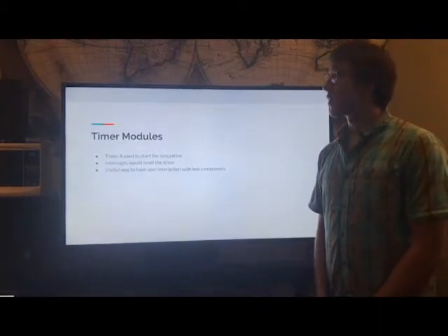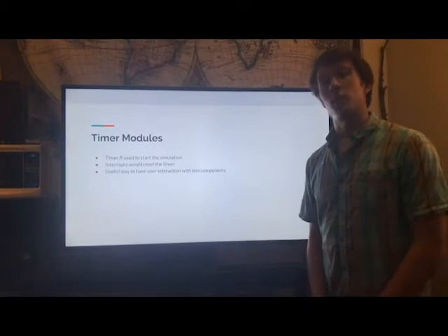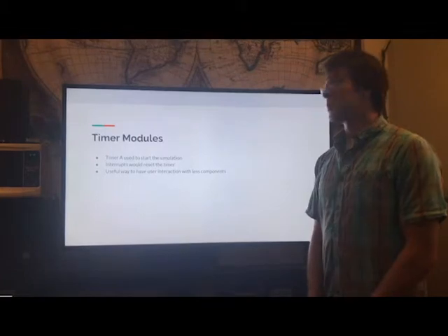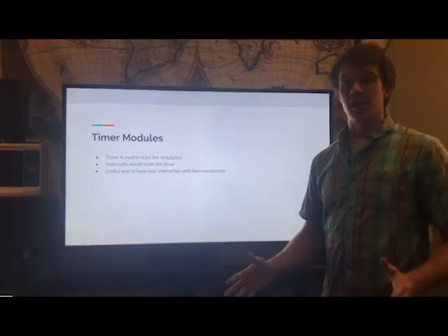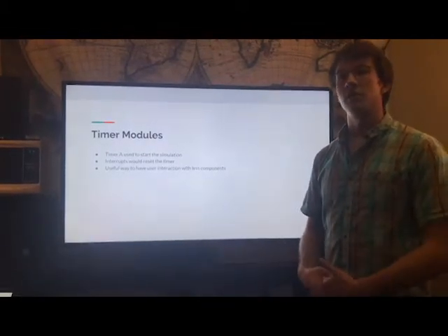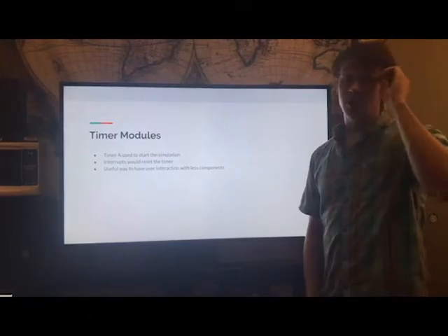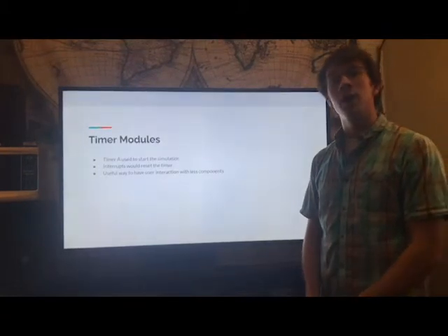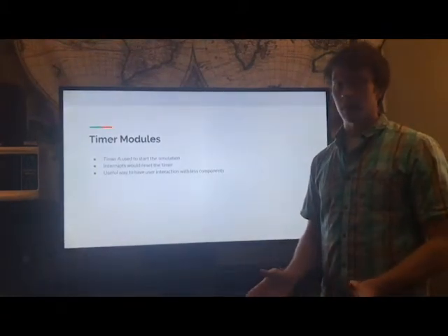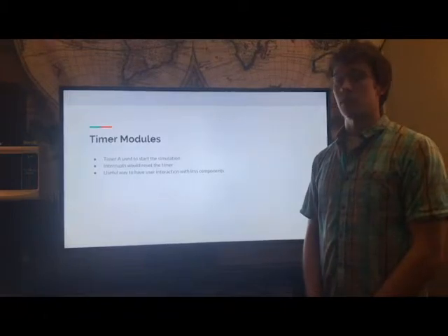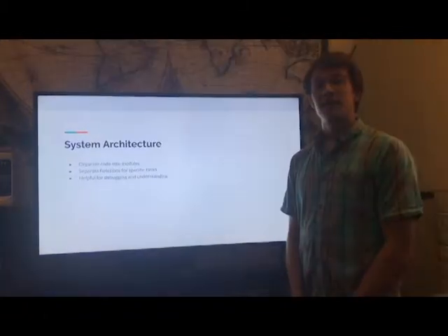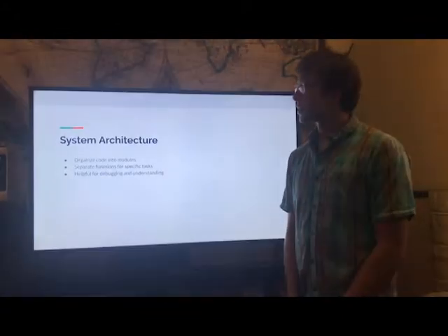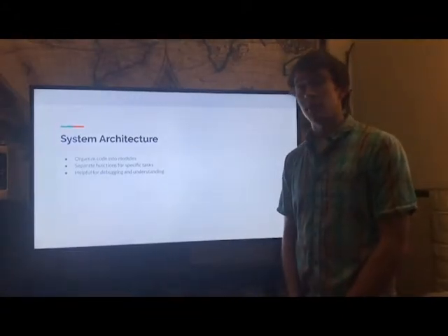In this way, timer A acted as a pseudo watchdog timer, where the watchdog timer was getting reset every time a button was pressed. We decided that this usage of an idle time from when the last button was pressed was a convenient and intuitive way for the user to interact with the cube. Rather than having another button or component to keep track of in hardware and code, we simply let the user sit and wait without pressing a button for a short amount of time, and that signals to the cube that the simulation should start. Extending past the individual techniques that we've learned from previous labs, this project is really an accumulation of all of our coding experience in embedded systems.